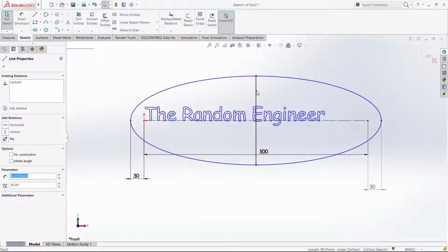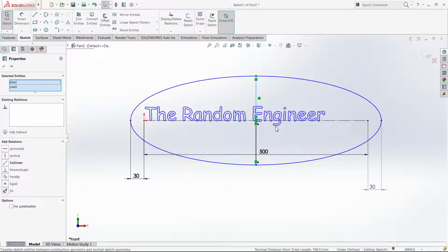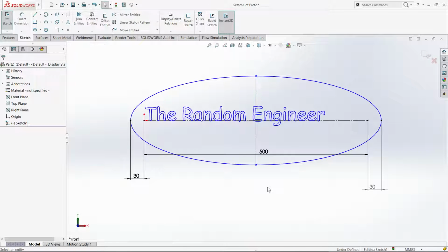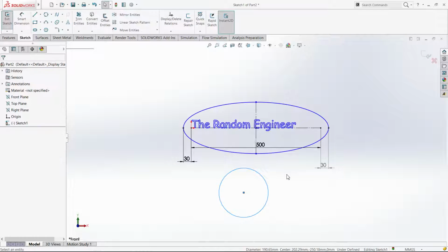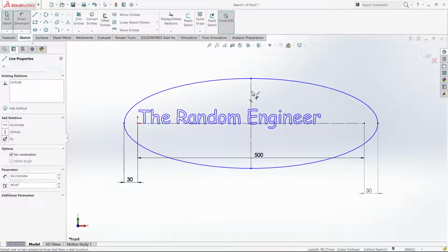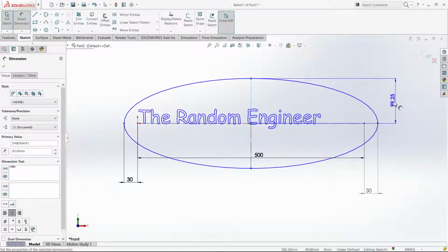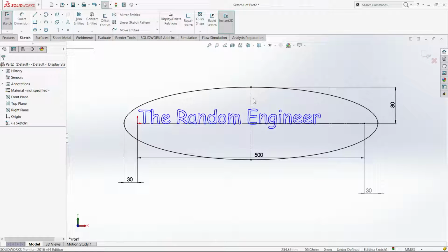I'm just gonna do this as a reference. So this is where, for example, construction geometry comes into account. You can select the 2 lines, make them construction. Over here, you can make a circle a construction line just by clicking on this icon, and you see how it's dotted now. That's a construction geometry. So since these 2 are equal by default by the definition of ellipse, you can just say you want a value here, and it's gonna make this line 82.